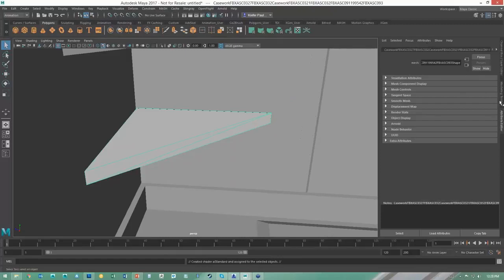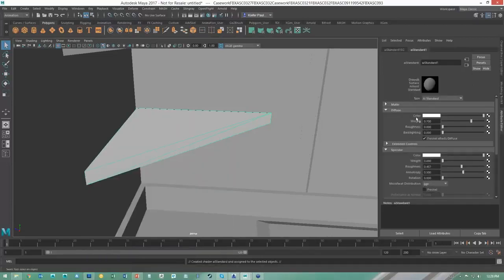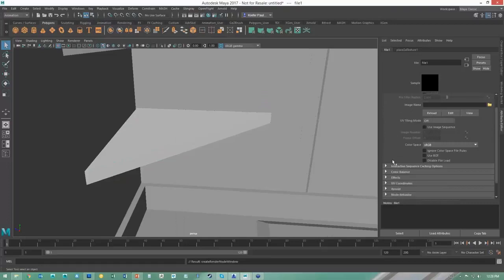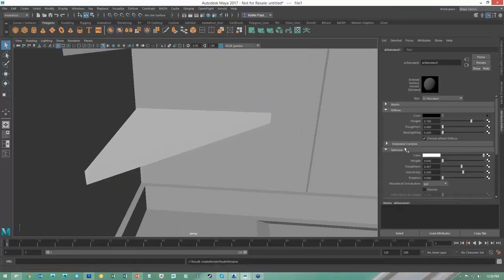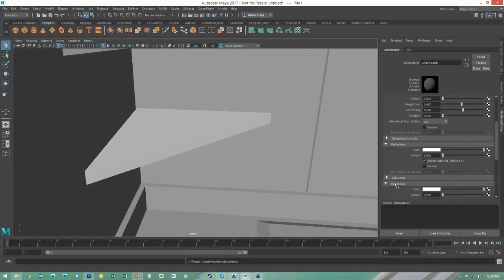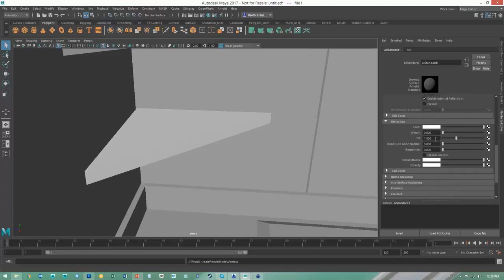And if we get to the component attributes for material attribute, we'll see the material attributes for the Arnold materials. You got your basic color. We can select this and map it to a texture if we would like to. The specularity, as well as the weight of how much you want that thing to show specular color. Reflections and refractions for when light passes through it. If it was a glass object, you'd want it to refract light. And the index of refraction, you can set that to be an exact number.